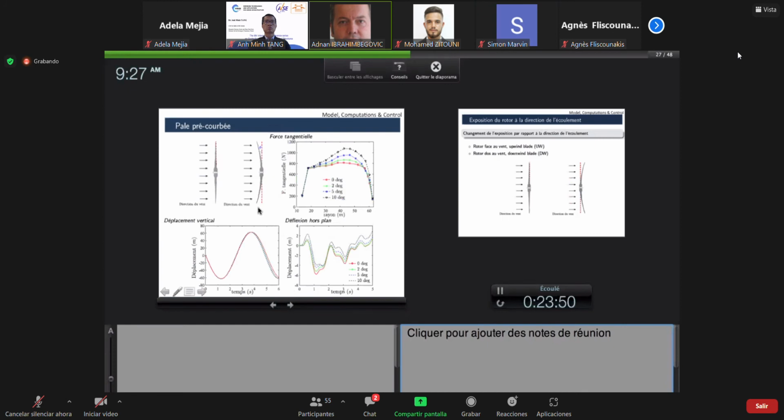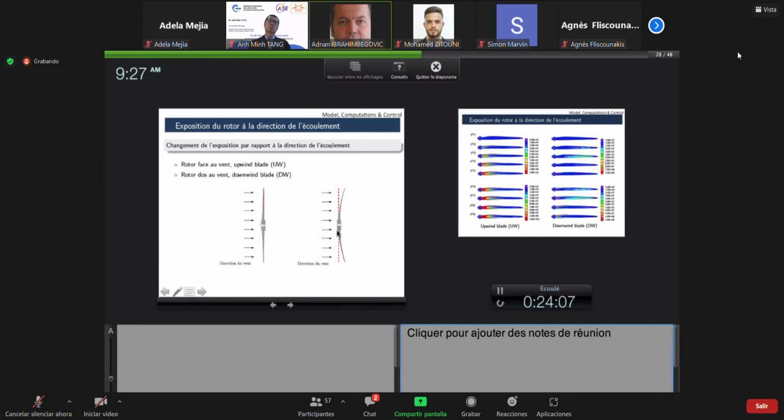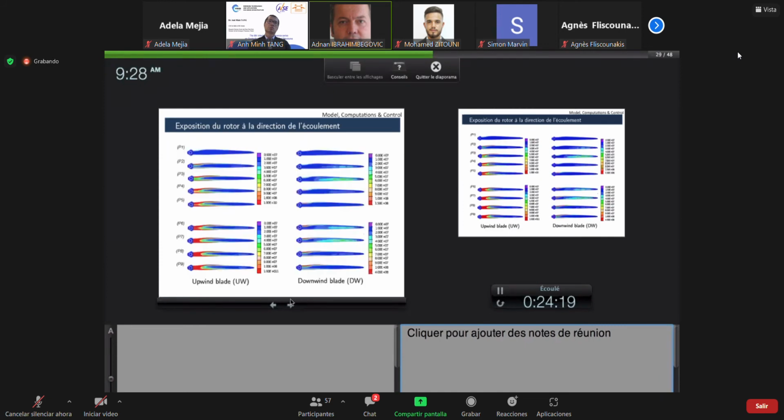And you can see we were playing with what form to give to these blades. You can keep them straight, you can kind of curve them in the direction of the wind, in which case, of course, you kind of reduce the tangential force to the blade, or you increase it, depending on what you're doing. And we're also playing with how to curve it in the opposite direction. In other words, when the wind is hitting the back of the wind turbine, given that these are very large, let's say, cantilever beams, these are 100 meters long, you can have very sizable bending effects.